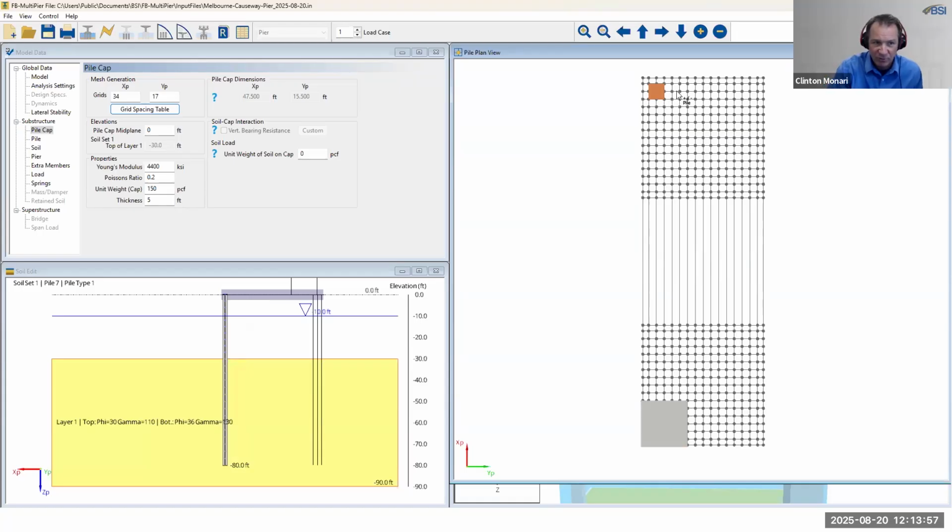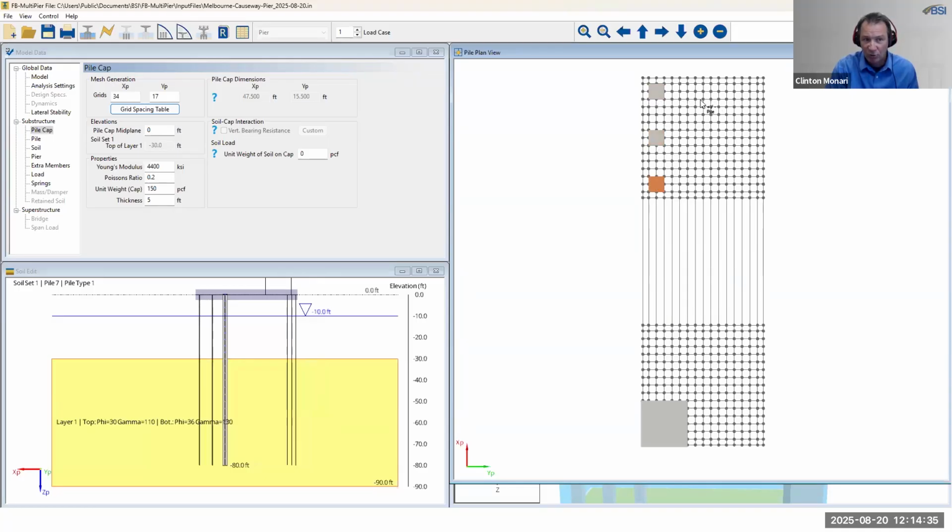And for this particular pier, we want 4 feet in between each pile face. And we know that most of these grid points are a foot apart, other than the ones that are pretty obvious. There's some 9 inchers here at the edge, and then there's this one big one in the middle, but we can count 1, 2, 3, 4. So this would give us 4 feet, right? I'm just counting the spacings here, 1, 2, 3, 4. Then we're going to want another 4-foot gap here, 1, 2, 3, 4. So we're going to put one right here, okay? And then we're going to repeat that.